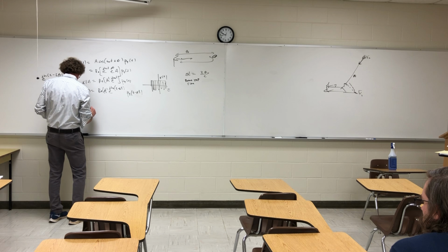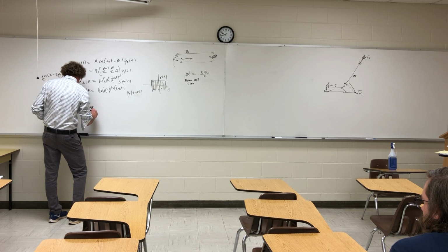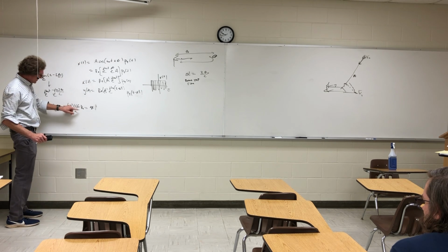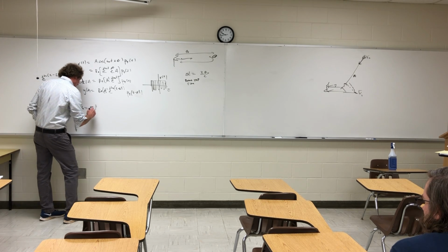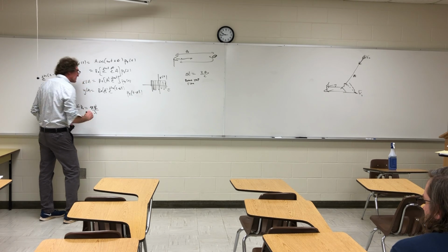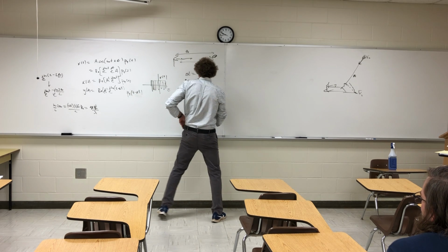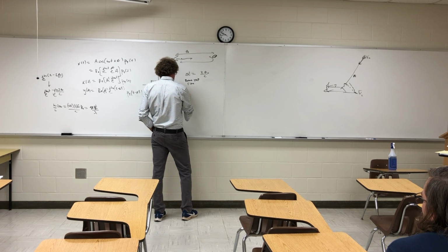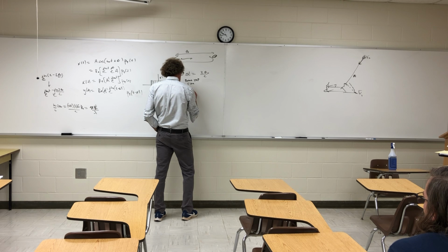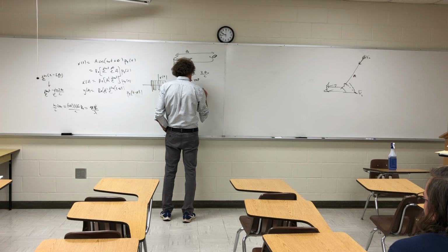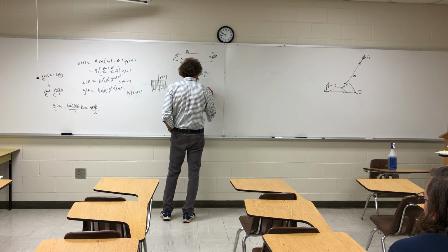And the way he puts this in the book, he puts this as 4 pi, and because c over f0 is the wavelength, you'll put 4 pi r0 over the wavelength, and that will make this signal y of t equal to simply the real part of A prime times e to the j omega naught t times e to the minus j 4 pi r0 over lambda.